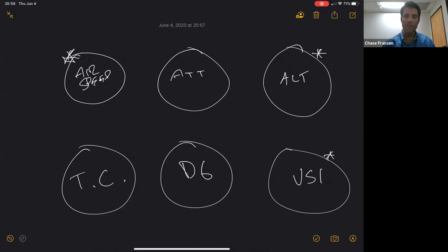So you've got your pitot tube on the outside of the aircraft. On the tip of that pitot tube, facing forward, is the ram air port. It's a mouth, if you will, gathering air molecules that you're shoving into it because you're flying along at 100 knots. There's also a static port that is measuring the atmospheric air pressure. That static port is not a mouth open to the air molecules flying at it. It's just hanging out, measuring the ambient air pressure. The altimeter and the VSI only care about the static port.